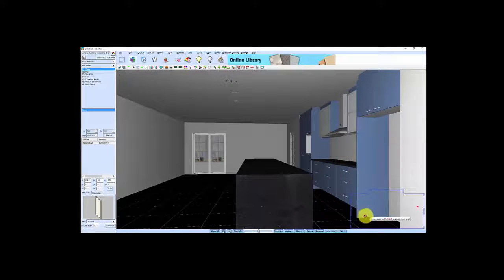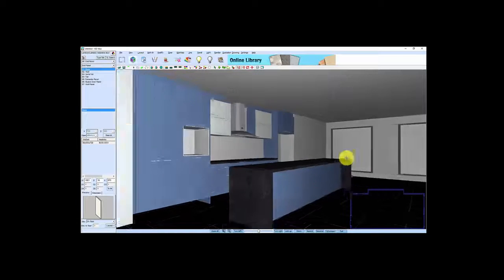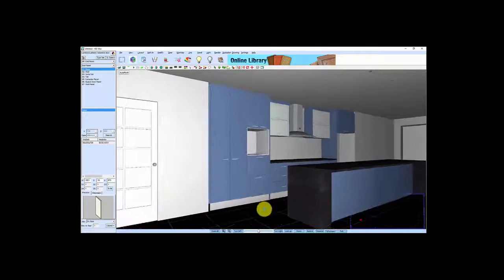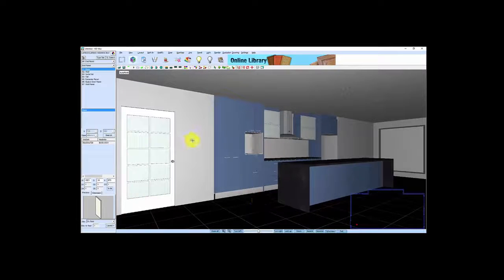Right. So now we are starting to get the basis of a kitchen. You can see from there we've got our island bench. What I'm going to do now is put in the kickers. That is an option with the kickers, the same as what we have with the benches. There's an automatically install next door to it, so we go auto install plinth. Select that, and that'll automatically install the kickers at the color and the dimensions we set up.